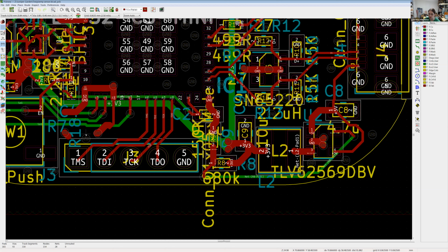When you program the whole lot, you plug into one of the devices, and then you send a command to program X number of devices in a chain, which you would know beforehand. So if I've got maybe 10 in a panel, then I would be able to program an initial load into the entire panel all in one go, which is really nice for designing for manufacturability.